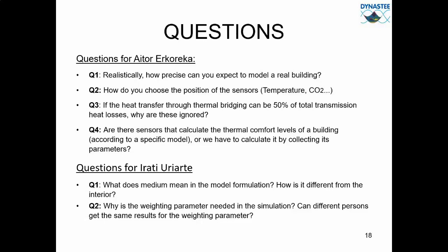But for the comfort part, you usually have in the ASHRAE documents some specifications that permit you to know if, with a certain temperature, a certain relative humidity and a certain activity level, you would be in a comfort zone or not.